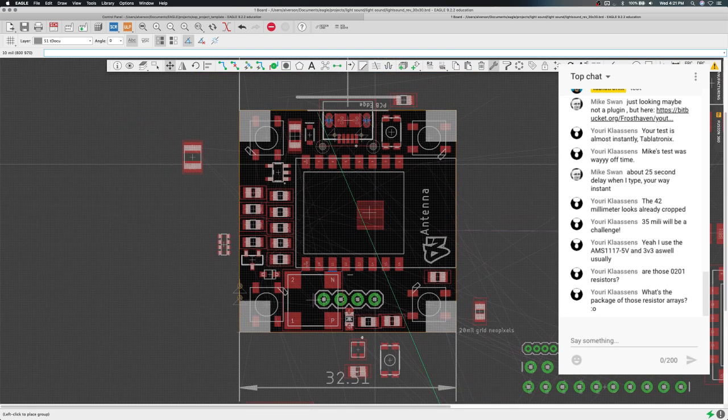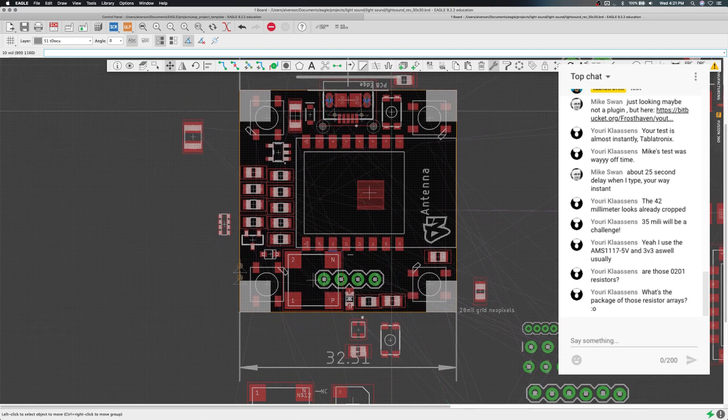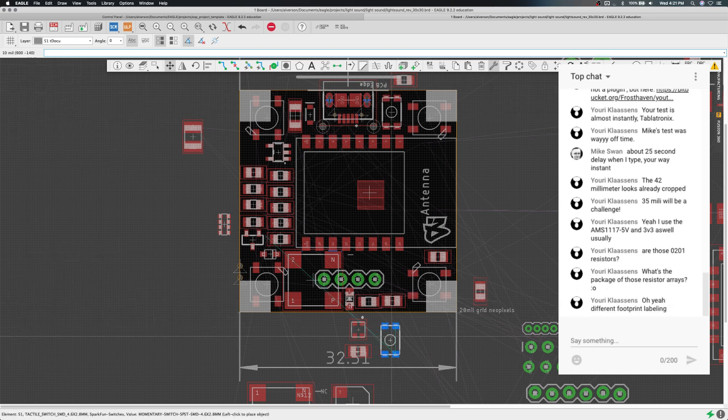So that gave me quite a bit of room. And then I want to keep a button on there that can do reset or GPIO. I thought about putting another button. I could maybe put it over here. But then that's another pull-up resistor. So I might just leave that out for now and just do one button that can be jumper switched between reset and GPIO. So if I put this in an enclosure that has like a little tab, then you can push on the enclosure and have it push the button. I thought that would be cool.